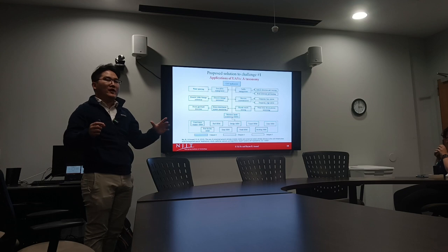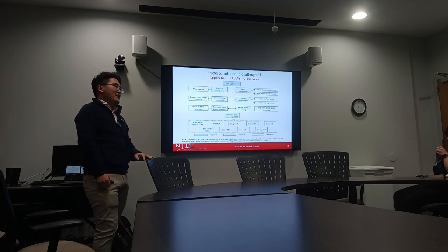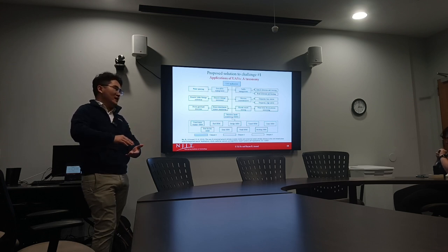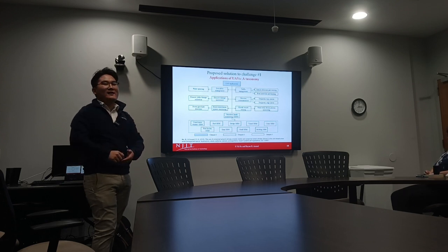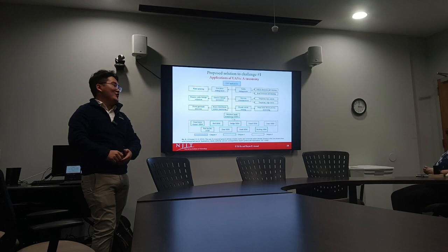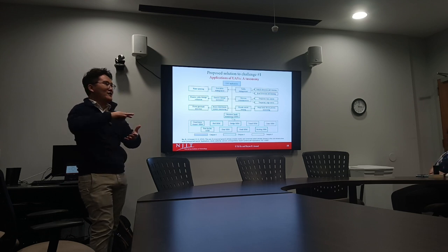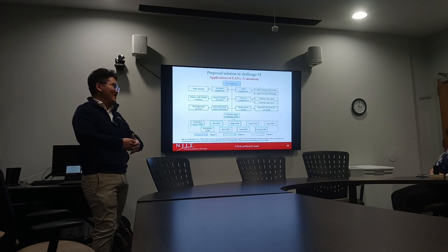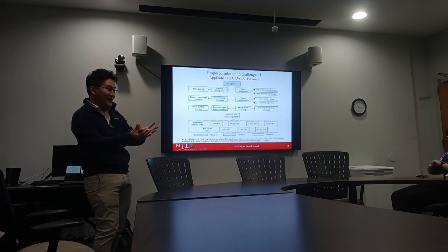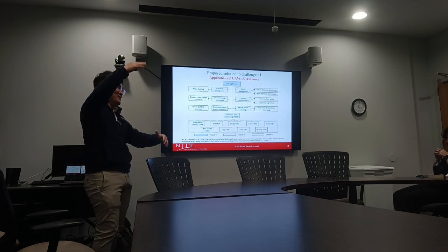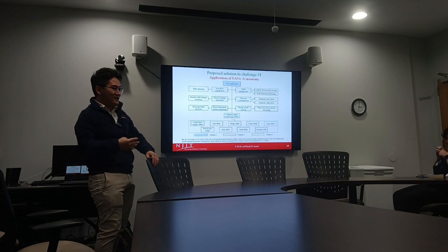We deploy a drone with a thermal imaging system, so it can capture the environmental heat, because OSHA has some standard for heat stress. Once the heat stress reaches 88 degrees Fahrenheit, you can take measurements. How? For the project I did, it was to trigger the water spray functionality of the drone. The drone would also carry a small water tank. Once it detects that in this region the heat stress is above 88 degrees Fahrenheit, it sprays water.